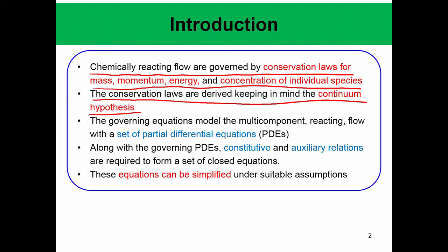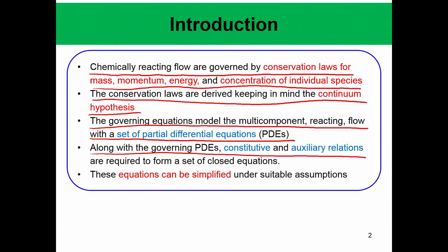which is mass per unit volume, and then the governing equations model the multi-component reacting flow with a set of partial differential equations. We will start with integral equations and then move on to partial differential equations, and along with the governing partial differential equations, the constitutive and auxiliary relations are required to form a set of closed equations.